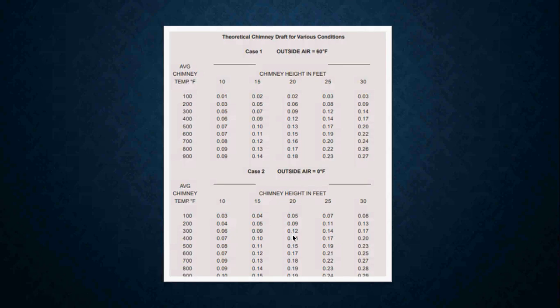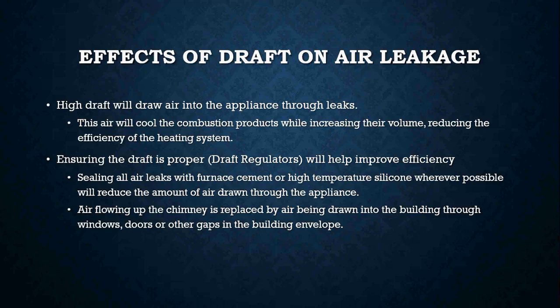That's because of the change in temperature, change in humidity, the change in the air quality that we're dealing with from one day to the other. So chimney draft is going to change no matter what we do. What we've got to do as a mechanic, HVAC guy, is try to fine-tune these things to where we can get them at their highest efficiency with very little issues. It can actually be very difficult depending on the situation.